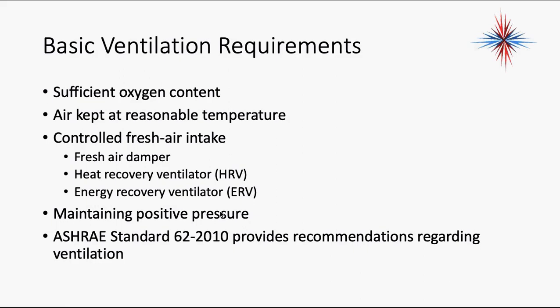Okay, ventilation ensures sufficient oxygen content. In other words, people aren't falling asleep at their desks. Air is kept at a reasonable temperature. We have a controlled fresh air intake. Okay, we have fresh air dampers. We have heat recovery ventilators. We'll talk more about those, HRVs. We have energy recovery ventilators, ERVs. Okay, we maintain a positive pressure on the indoor environment.